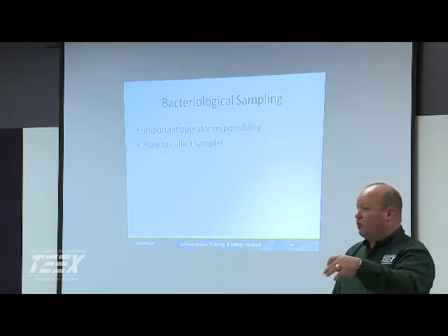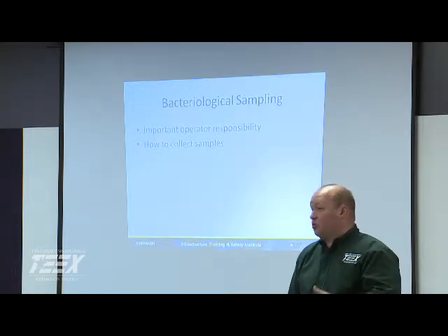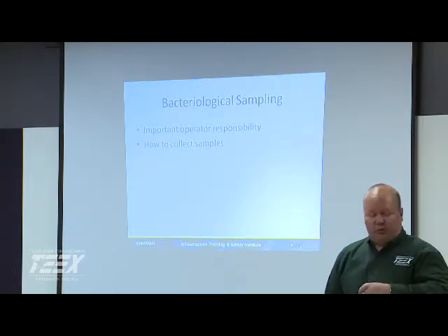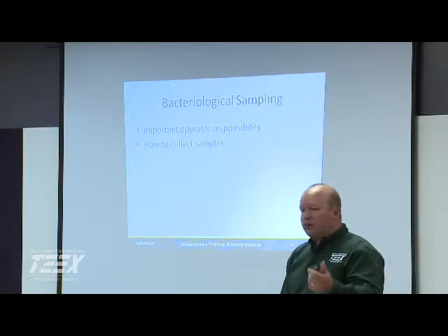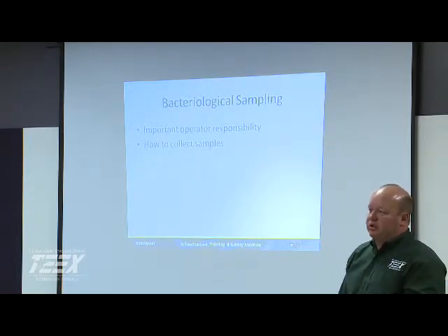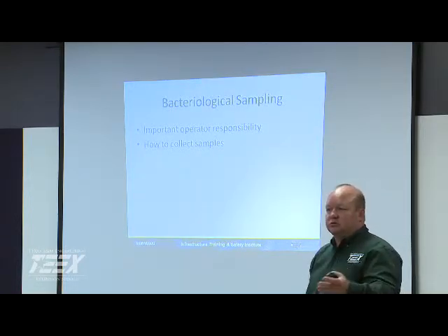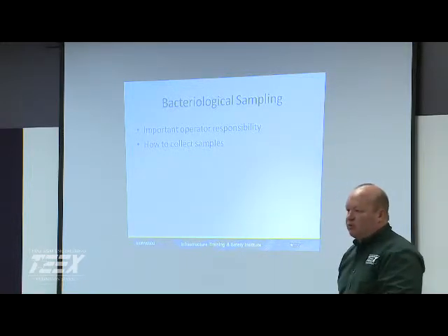I was in the lab that day doing the results, and I had like 10 or 12 positives for total coliform. Luckily, it was just total coliform. But we had to go through all the paperwork of getting them invalidated by the state, and all the repeat samples, on and on, because somebody didn't understand the process. So especially for bac-Ts, I'm a real stickler.